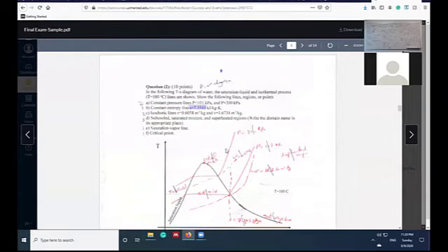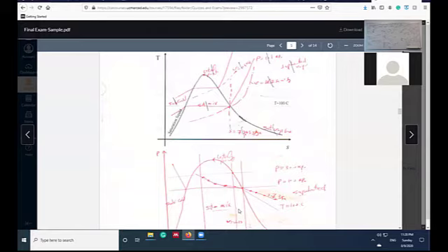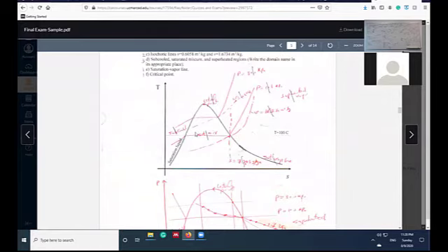Here is more clear. This is the exam. This is additional for you to know what's going on. We have 2 lines, 3 regions, 1 point: subcooled, saturated mixture, superheated. Everything here is superheated, like air. Now, this is a saturated mixture. We have some vapor and some liquid with quality x, how much vapor mass to the total mass. And compressed liquid, which is pure liquid, but at lower temperature than the critical or transition temperature. And this is the critical point. 3 regions, 2 lines, 1 point. Okay, guys?